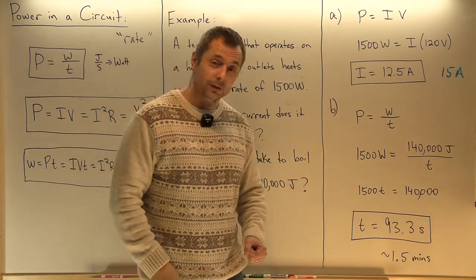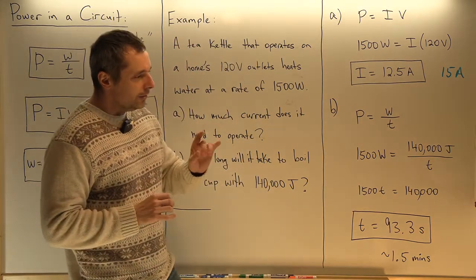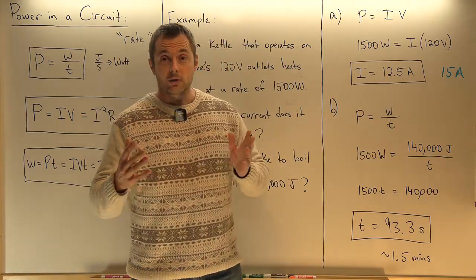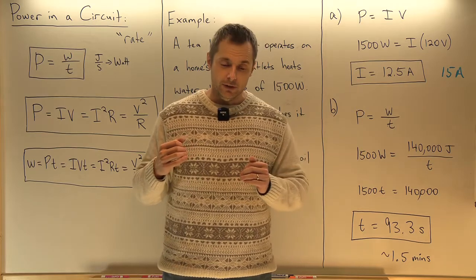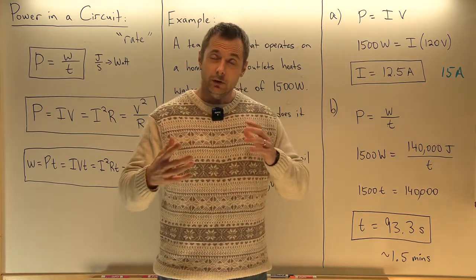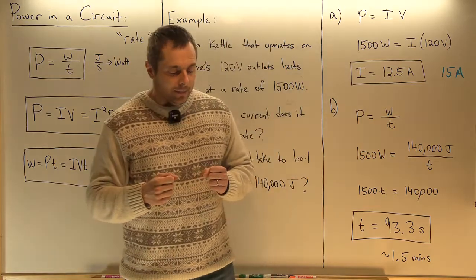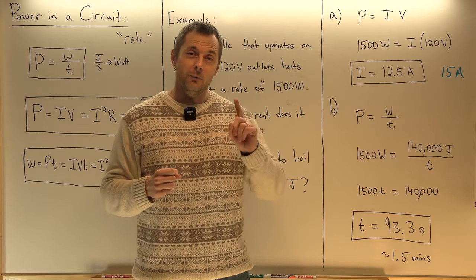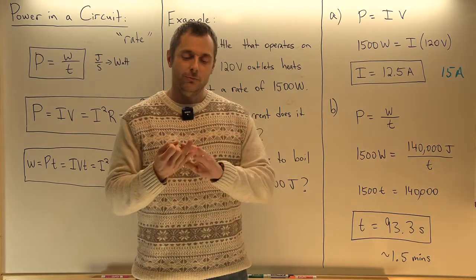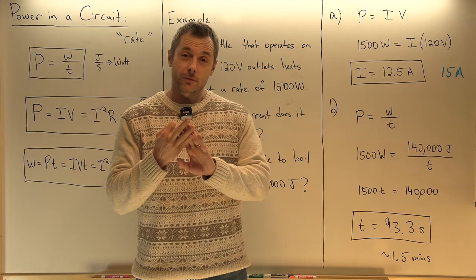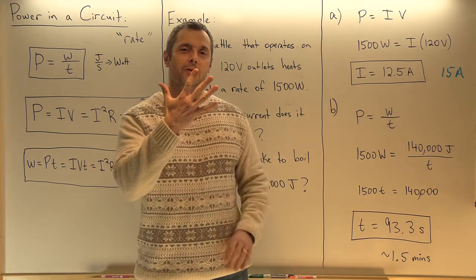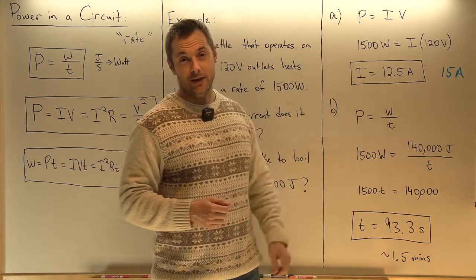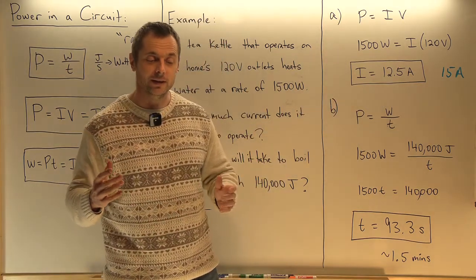So you try to boil water and blow dry your hair, and you're going to completely overload your bedroom's electrical circuits. Okay, so interesting. Another interesting thing I want to point out, a little aside. The house I live in was built in the 1950s, and as I was looking at the circuits, I discovered that more than half my house was wired on one 15 amp circuit. Two bedrooms, the living room, the basement, and the laundry room, all on one 15 amp circuit. I boil a cup of water, and I'm almost overloading three quarters of the house's electricity.